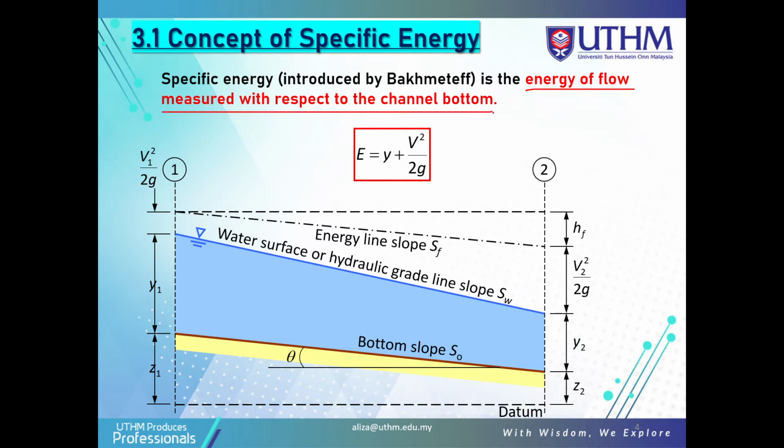In case your test or final asks you to explain what specific energy is, you can explain it as the energy of flow measured with respect to the channel bottom, and put this formula: E, the specific energy, is equal to y plus V squared over 2g.